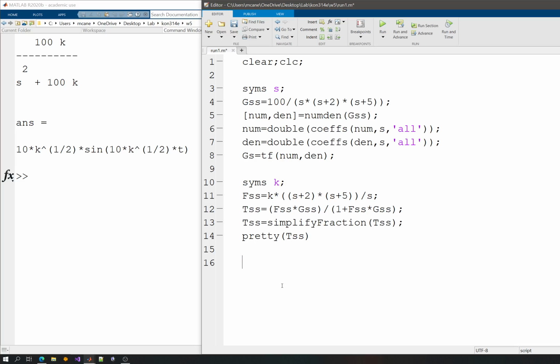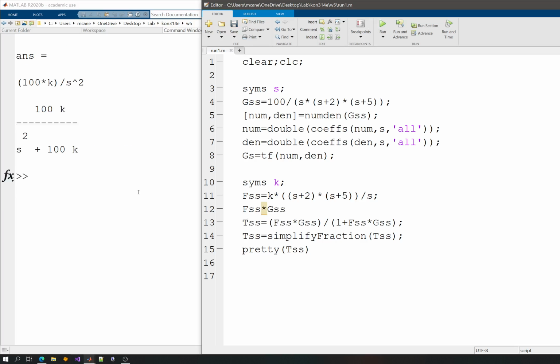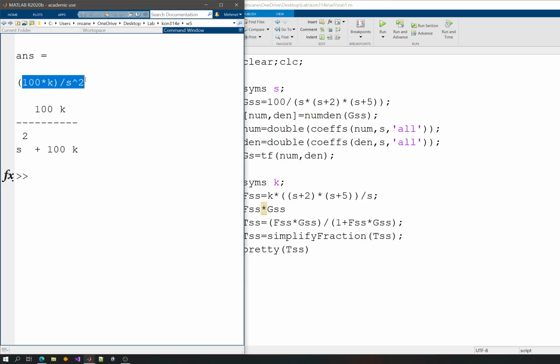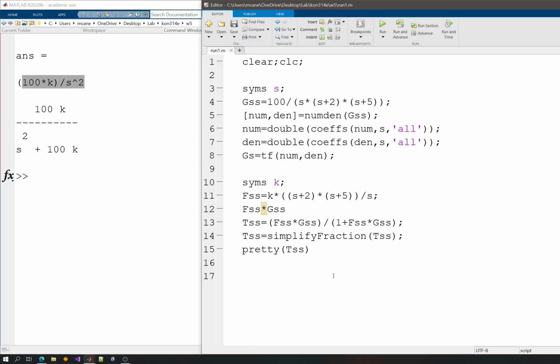And if I plot the root locus of this, which I'm by the way able to do, since it's only necessary to look at F(s) times G(s), and I can plot the root locus of this, and I can see that this is basically 100k divided by s squared, which means that if I'm looking at the root locus, I can use a transfer function. You should omit the k here. You will not use the k because you can't define the parameter k. And this should be the root locus that's representing my problem. Hopefully Matlab will be able to solve and show me that.